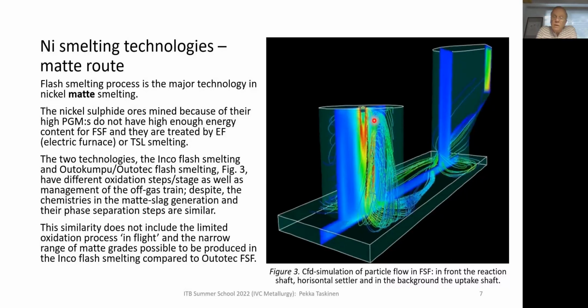Smelting reactions, heat generation, and use of oxygen take place within the reaction shaft where dry concentrate with fluxes is fed, and formation of matte and slag takes place in the settler below the reaction shaft, where these fine particles, after this partial oxidation, settle and start forming slag and matte in a similar way as in copper smelting processes carried out with flash melting technology.